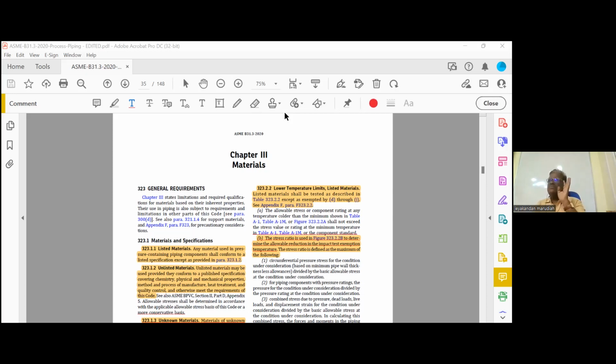If it is a fixed temperature, you can use any thickness of this material up to minus 50 degrees. Some materials are given a curve A, B, C, D. Curve means there is a table, so you have to refer to it, and the temperature will change based on the thickness. Actually, that is the exam question.